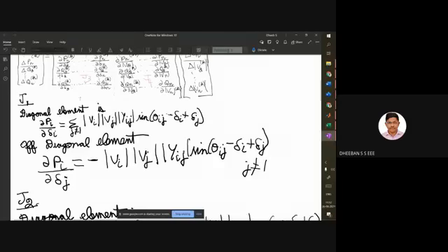That is for the diagonal element. What we'll be doing is it is nothing but your self admittance, whereas your off diagonal elements are your transfer admittance. So with respect to your admittance matrix, here you will be getting summation, that is the buses connected to the particular bus.